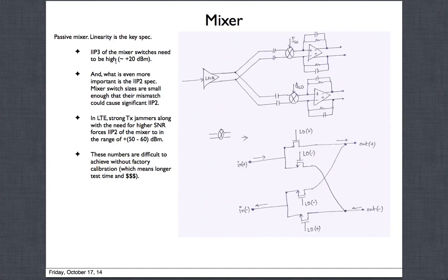Now what does that mean? This is a switch. The lower the resistance is, the better the linearity is going to be. That's just the fundamental thing about these switches. So how do you make the resistance lower? Well, you increase the overdrive VGS, turning it on with a strong overdrive. Well, there is a limit to how much it can sustain before it breaks down in today's technologies. So you can't just put a huge voltage here. The only thing left is to increase the size of the switches. But when you increase the size of the switches, then your power goes up.